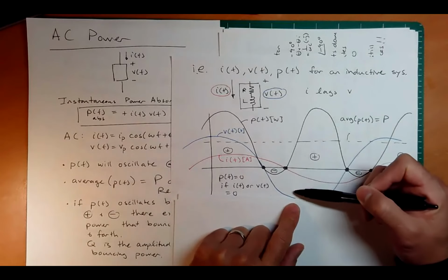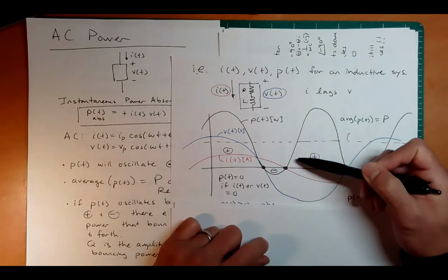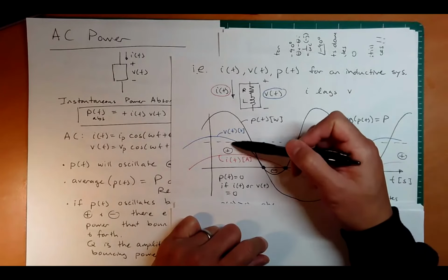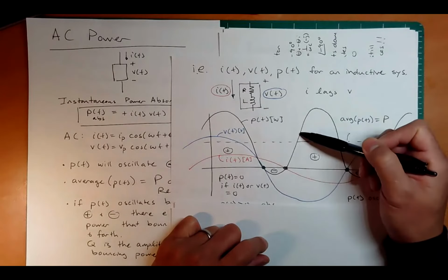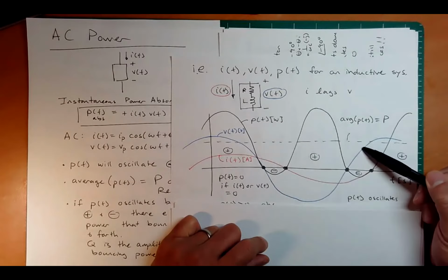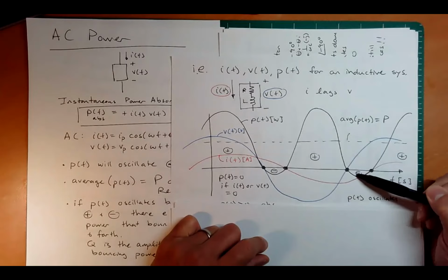Look at this. Negative and negative. We get positive. Okay. So the power kind of rectifies itself. 2 positives makes a positive. 2 negatives makes a positive. Okay. And then we come right back here. Now this time the current is negative, even though the voltage is positive, and we get negative power.